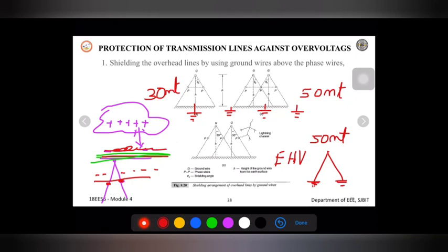That's the reason the pole also will be grounded. So apart from the ground wire, which will be grounded directly, the tower also will be grounded. All 4 legs of the tower will be grounded. In the next case, we'll see there is one more called a counterpoise wire, and other things that also help to ground the transmission towers, so that if a fault occurs anywhere, it can easily be grounded, and I can protect my transmission line.